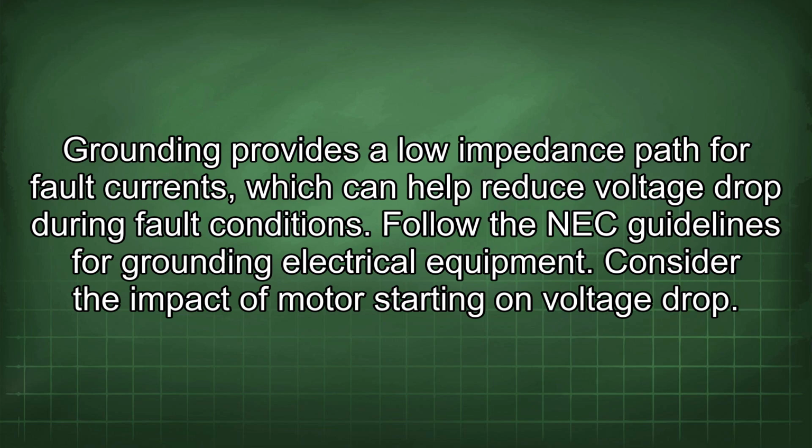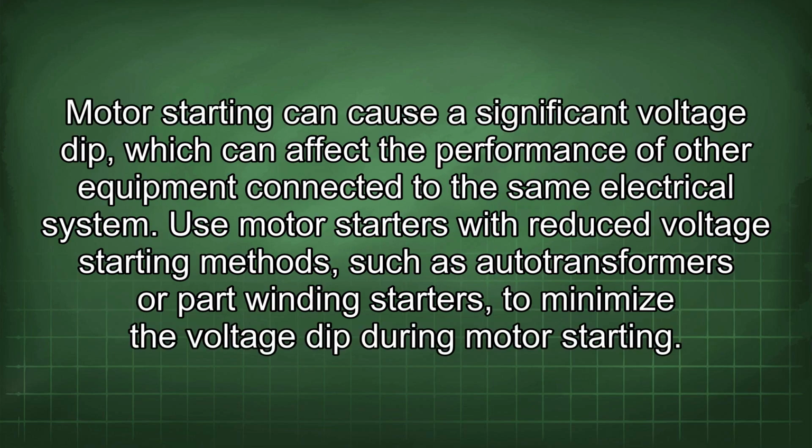Consider the impact of motor starting on voltage drop. Motor starting can cause a significant voltage dip, which can affect the performance of other equipment connected to the same electrical system. Use motor starters with reduced voltage starting methods, such as auto transformers or part winding starters, to minimize the voltage dip during motor starting.